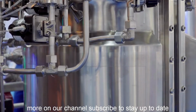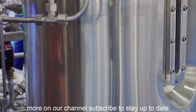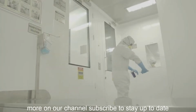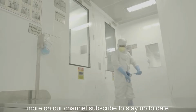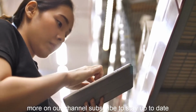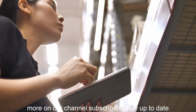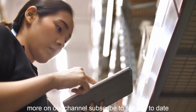For example, an SOP for cleaning a mixing tank would detail the type and concentration of cleaning agent, contact time, temperature, rinsing steps, and verification methods, e.g., visual inspection, swab testing. Personnel performing the cleaning must follow every step in the SOP and document their adherence. This rule ensures that every time a task is performed, it's done the same way, minimizing variability and potential errors.